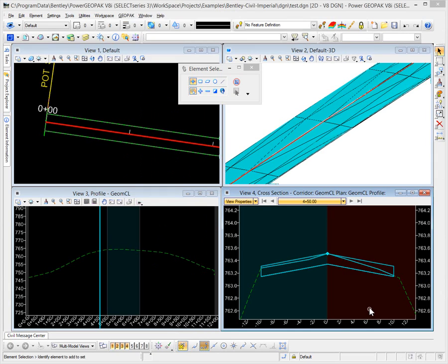And so taking a look at the results, you will see that we have two components, but the bottom now has a corrected cross slope, which is typically the way we mill. And then the top also has the corrected cross slope, in other words, following the component. And so this gives us, again, the two different components to be able to calculate those quantities separately, making sure that you have the stripping component turned on. But both the top and the bottom are now following the corrected cross slope. So the milling utilizes corrected cross slope as well as the leveling binder.